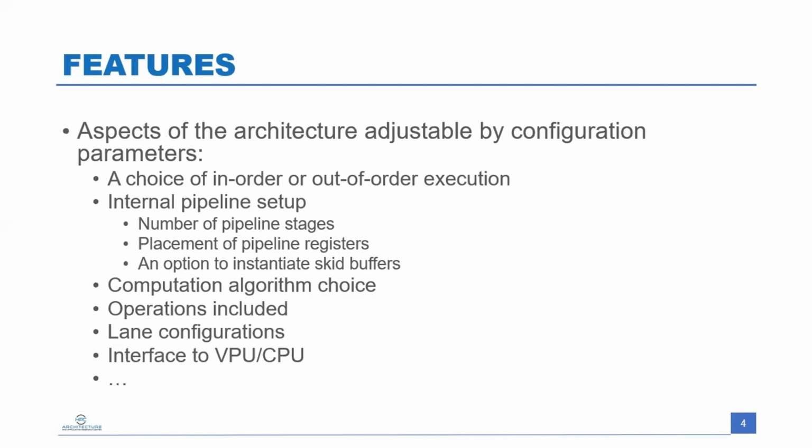One of the key features is that right now we can really configure the design related to pipeline stages. So we can adapt the design to future processors that might require more or fewer pipeline stages, or have different interfaces or different timings, because we are more aware of what we can control and let the synthesis tool do the more predictable things.